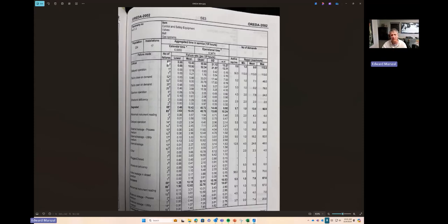And for all of the failure modes, of those 224 valves that were in operation for 6.5 calendar years on average, since different data sets are going to be for different durations, there were 87 critical failures. So failure to close on demand, 52, failure to open on demand, 26, spurious operations, 6, and so on. So this is pretty good, and if you look at Kenexis's generic numbers for a ball valve, we will show you the OREDA data because it's pretty good.